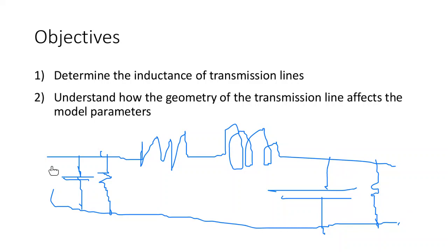So if I asked you what parameters we can neglect from this, these are the type of questions. It's like interview questions. If you want to work as a power system engineer, or you want to teach power, for example in the power lab, you need to understand. So what parameter can I neglect on these? The conductance. The what? The conductance, the G. Very good. Yes. So I can neglect the G, this one here.